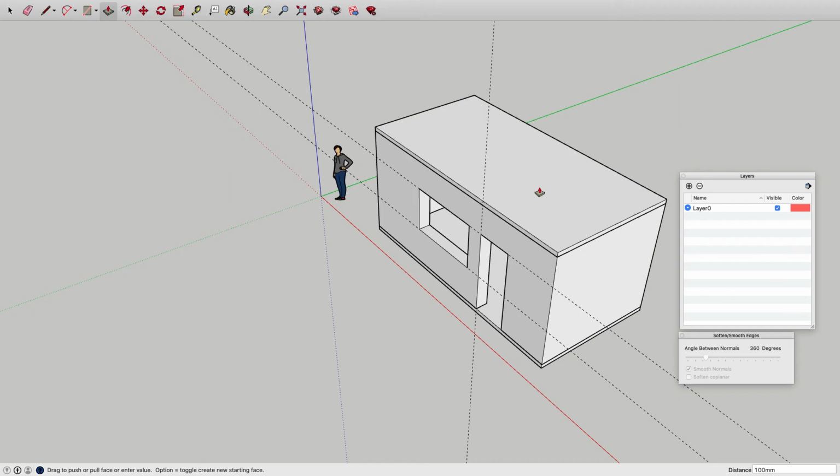Okay? Now for those who are adding a floor on, a standard floor between 2 floors, standard space from that for all the beams and everything is 300 millimeters. Okay? But I'm just going to do 100 because I'm just representing the gutter. Okay? Right, so now I need to put a roof pitch on.